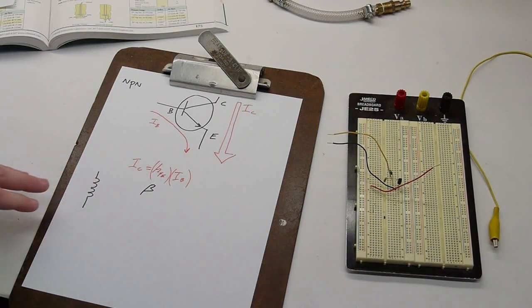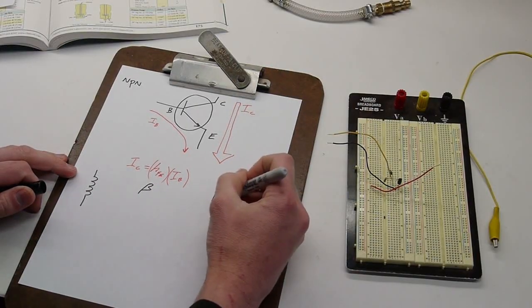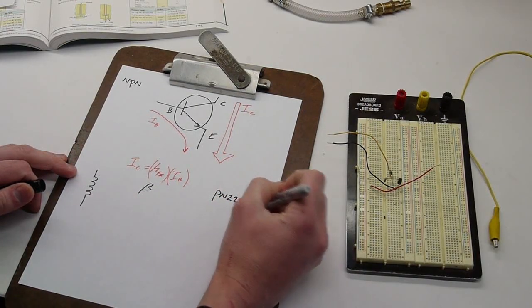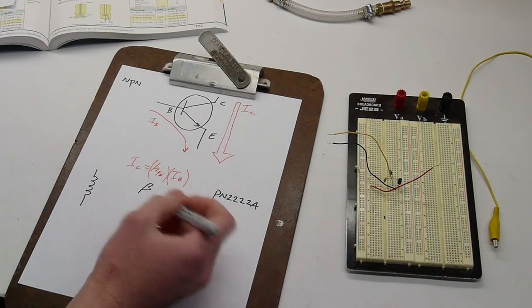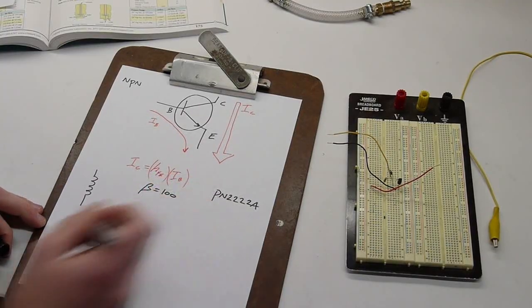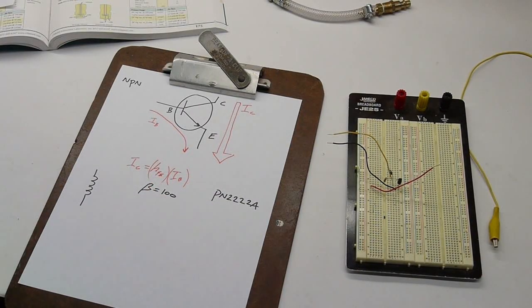What we're going to do here is pick a transistor, and this is a little bit where experience comes into play. I mean, there's thousands of transistors available. How do you pick one? Well, for hobby projects and sort of small scale design like this, there's really only a handful that come up. So I'm just going to say that we're going to pick the PN2222A, which is a really great low, medium power, very inexpensive, easy to use switching transistor. And it has a beta of about 100. We could be more conservative than that, but we'll just say beta is 100 for this particular transistor.